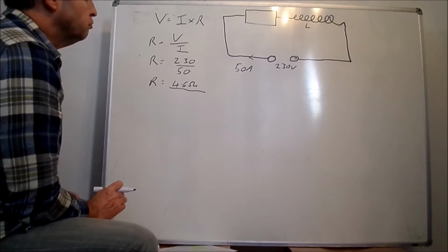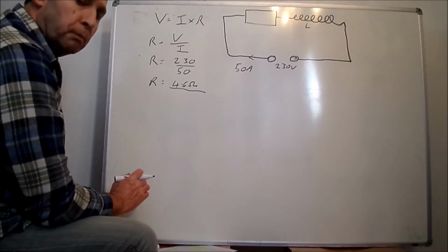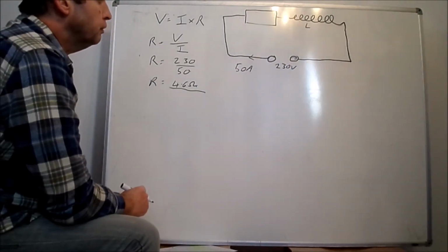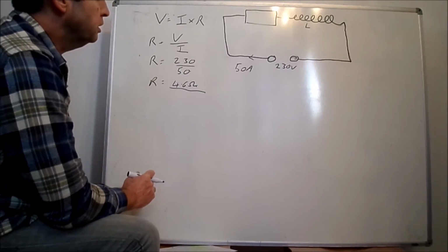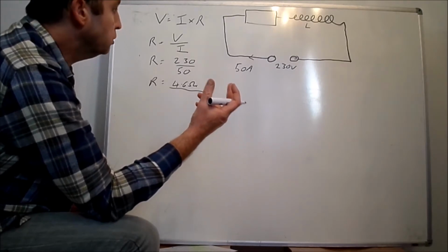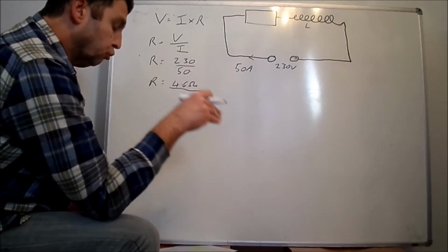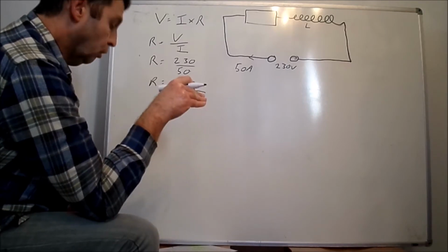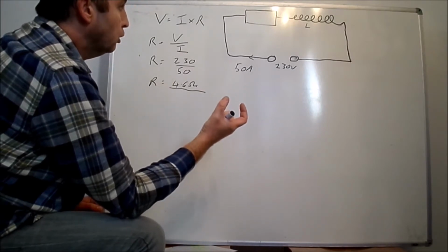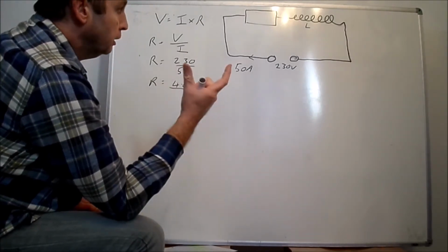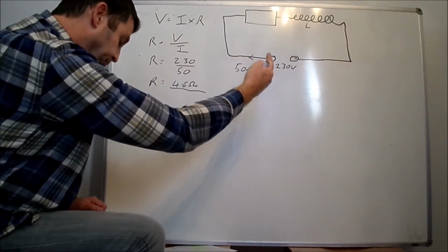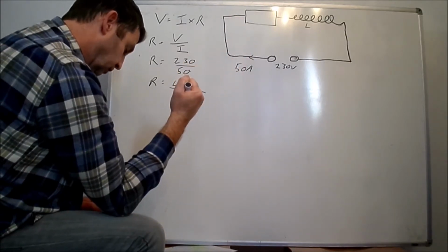Now, if this was running AC, different principles would apply, because this would now have a reactance in there. Your coil would have a reactance, which is XL, inductive reactance, and that inductive reactance would push against the supply current in the circuit, and then it would drop the value of the current due to the magnetic field expanding and collapsing around that coil. The magnetic field will form, it will collapse, form and collapse. That will induce an EMF which fights back against the supply, and therefore you get less current in there.